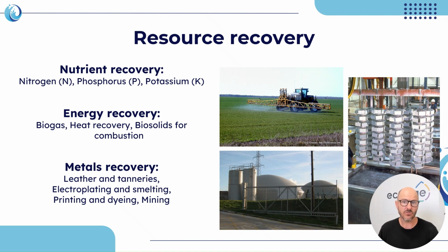One major energy recovery pathway is anaerobic digestion of sludge, which generates biogas rich in methane, which can be combusted on site to produce electricity and heat, offsetting plant energy demand and reducing greenhouse gas emissions. In addition, wastewater itself contains low-grade heat that can be recovered and directly reused for district heating, industrial applications, or to improve plant efficiency. And finally, after dewatering and drying, biosolids can be combusted to generate electricity or heat, with the added benefit of reducing sludge volumes.